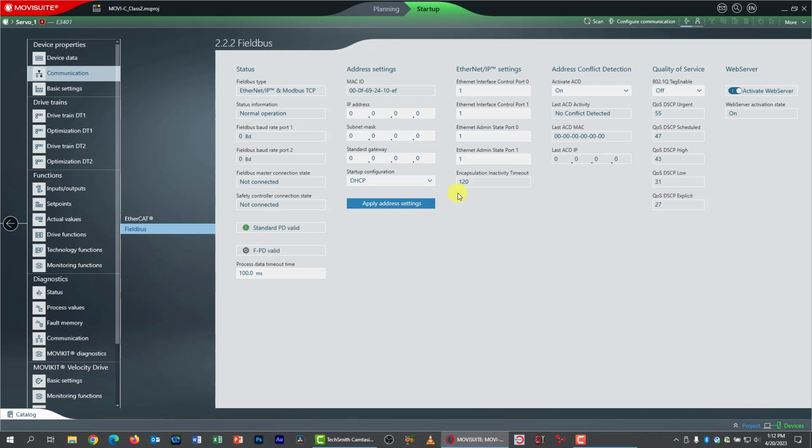So we're going to change it to the SEW Eurodrive default hard-coded address, which is 192.168.10.4. To do this, I need to pop this down and change this to saved IP address parameters, and I need to go up here now and key in my IP address, tabbing between fields, except when I get to the last one when I have to hit Enter. So I'm going to take care of that right now.